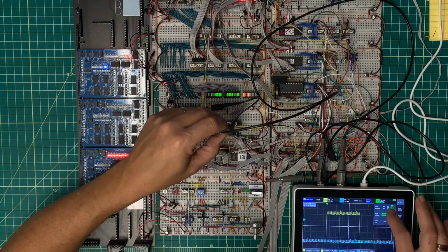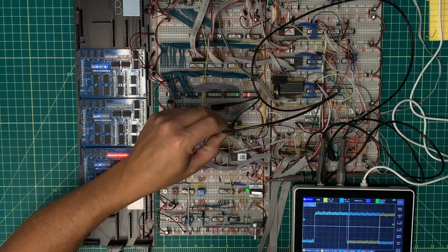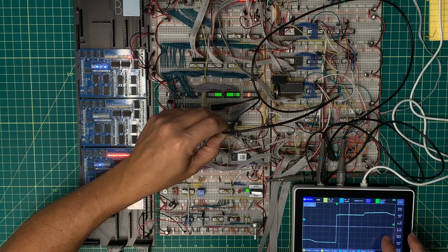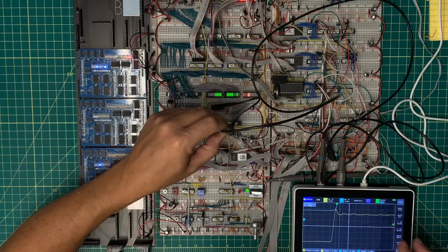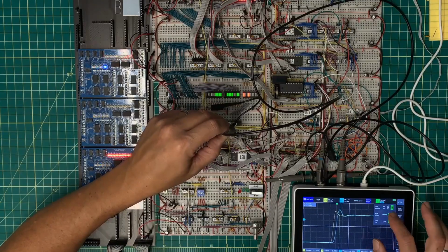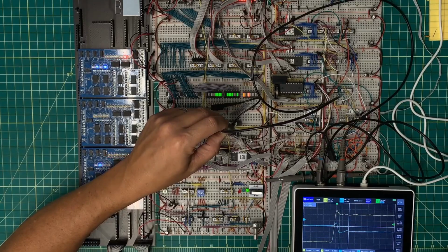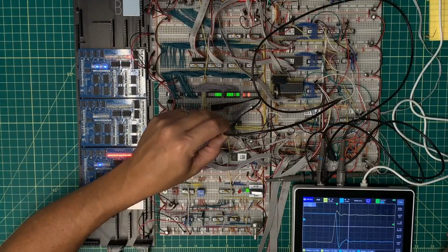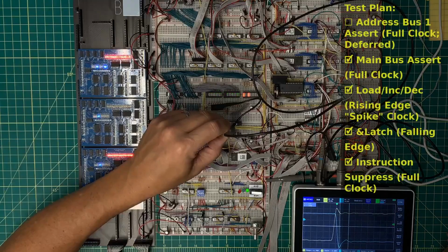And if I look at the timing of that, let me switch my trigger to be channel 2. On the surface, that seems to follow the entire clock cycle. If I now zoom in, and I've not done this, so I don't know just how close that is. 50 nanoseconds per division. Let me let that average back out. And I look like I'm running about a 25 nanosecond delay. Now if I switch to the falling edge, again, that could be about a 25 nanosecond delay. That instruction suppressed signal looks pretty good to me.